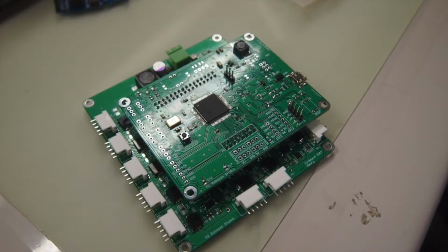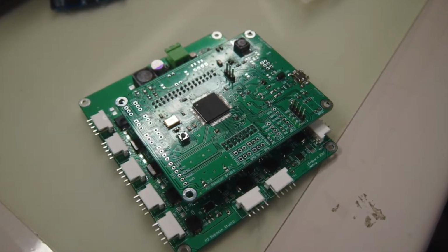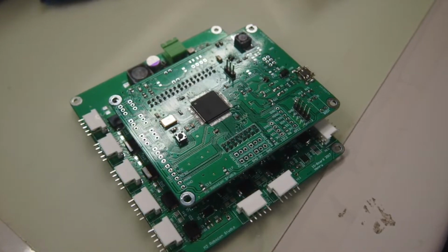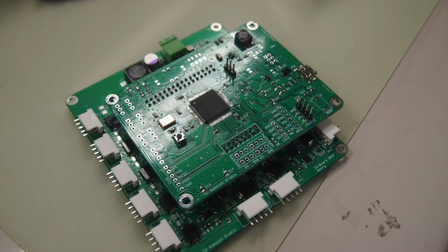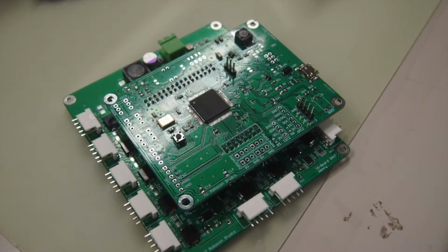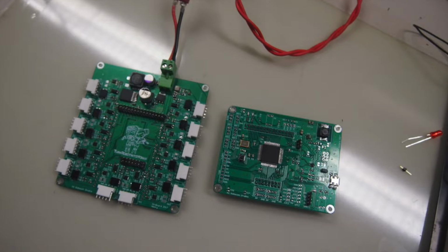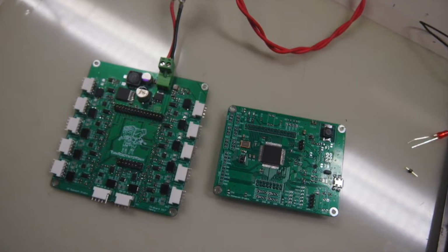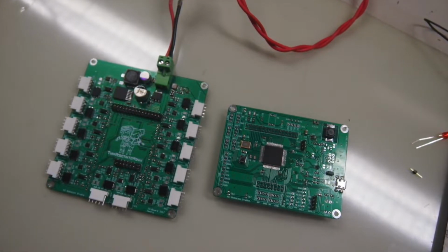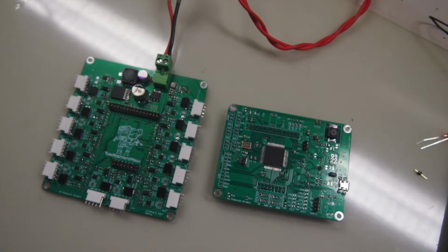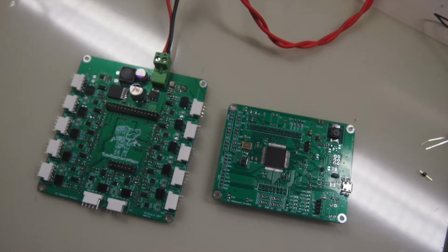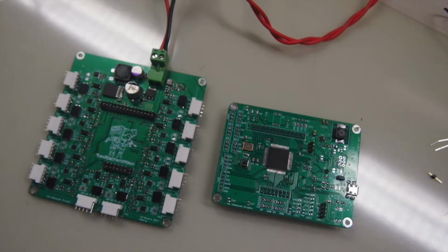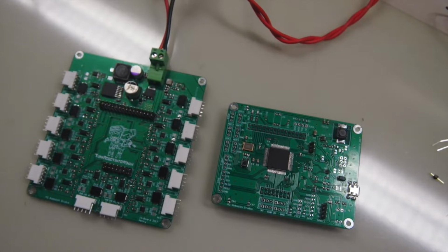We have designed a printed circuit board to construct the system. In this PCB, we have an upper layer consisting of the STM32F1, and a lower layer which contains 12 connectors for our auto lighting module. In the lower layer, it could supply 5 volts or 24 volts, depending on the load. The STM32F1 could drive it with an N-MOSFET acting as a low side driver. For the input part, the lower layer has optocouplers to isolate the STM32F1 from the input side, so that the input side could use sensors with different voltage levels without damaging the STM32F1.